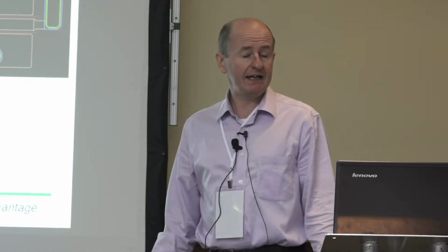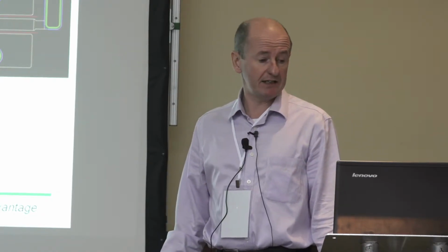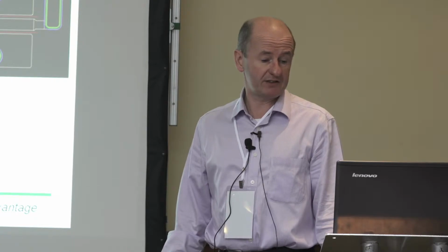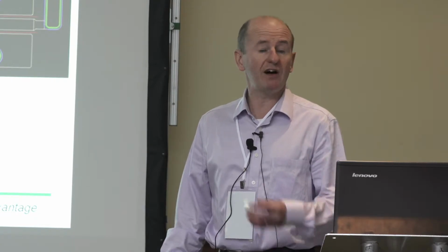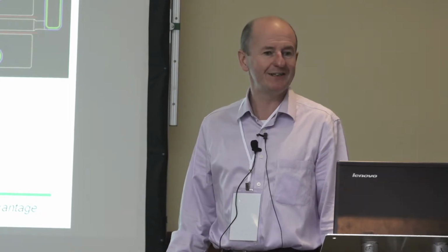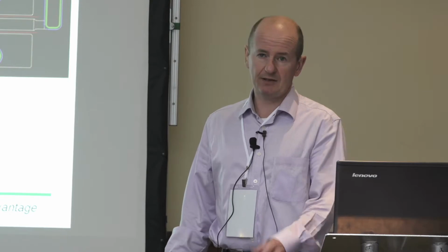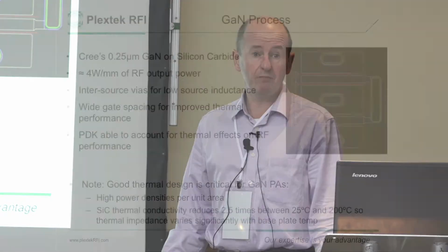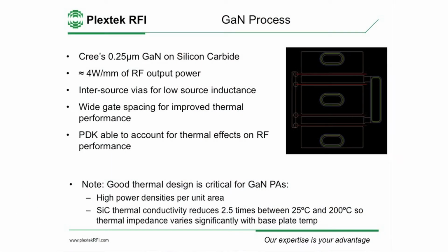The PDK that Cree supply is nice. It's got a facility in it to predict the thermal effects on the RF performance. You have to put in the thermal impedance of your transistor, which is down to the designer to work out, so it does require some skill. But given that, if you type in the base plate temperature, then the model will tell you how the performance varies due to the self-heating effects.